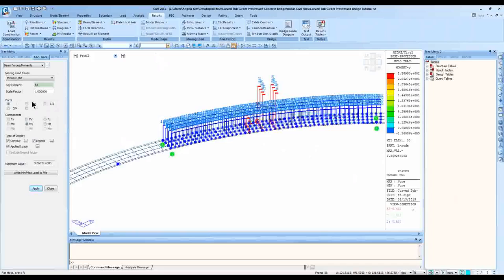And regardless, if you're wondering about concurrent forces when the reaction was the worst, you can find them all. Go to moving load tracer, find reaction, displacement, truss force, beam force moment. And for the beam force moment, you can not only do that for the bending moment, you can also do it for shear. But most likely, we are interested in taking the moment and also the reaction.